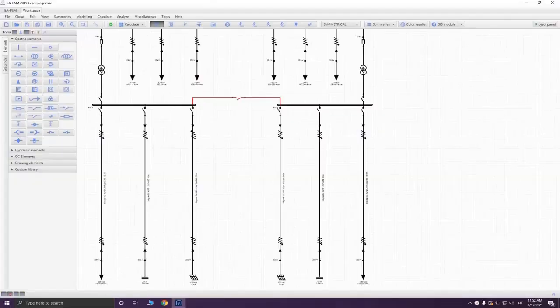Lastly, I'm going to talk about harmonics. Harmonics are generated by non-linear loads. This type of load is an inverter in your solar power plant. Harmonics cause a lot of troubles in the power grid. That is why we compensate them using passive or active filters. Additionally, harmonics generate currents that make up additional losses in your power lines and could overload your transformer.